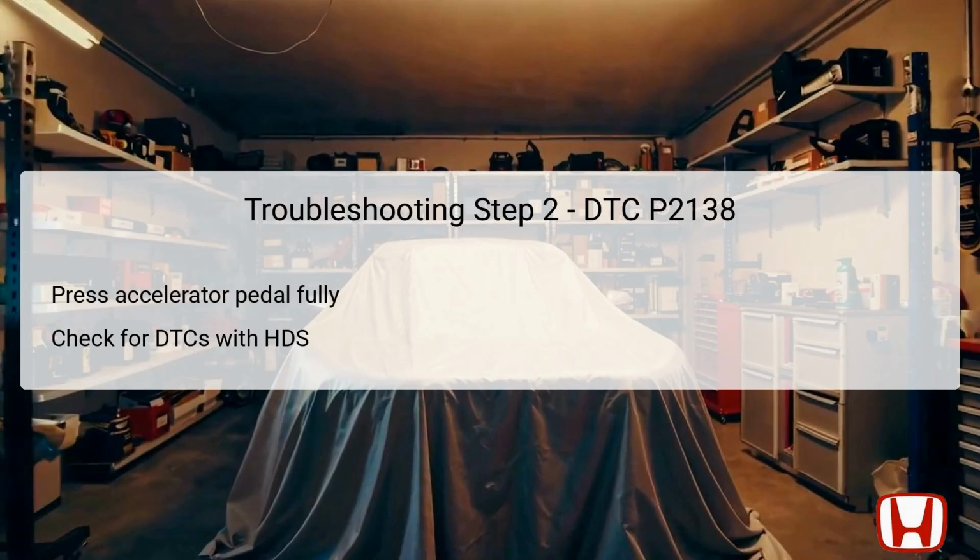This action simulates maximum throttle input, which is vital in evaluating the responsiveness of the APP sensors. After applying this input, use the Honda Diagnostic System, HDS, to check for any pending or confirmed DTCs. This analysis is crucial to determine whether DTC P2138 is still indicated. If the code persists, this indicates that there is a fault with the APP sensor circuit, either as a result of the sensors themselves or issues upstream that affect their performance.